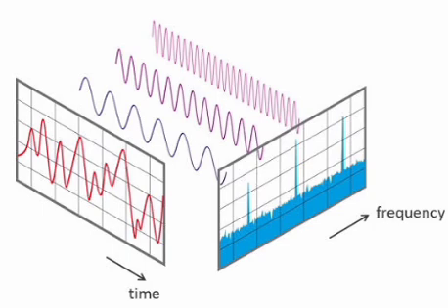It is bounded by the poles. If x[n] is of finite duration, then the ROC is the entire z-plane except possibly z = 0 and/or z tending to infinity. If x[n] is a right-sided sequence, and the circle |z| = a is in the ROC, then all finite values of z for which |z| > a will also be in the ROC. If x[n] is a left-sided sequence and the circle |z| = a is in the ROC, then all finite values of z for which |z| < a will also be in the ROC.